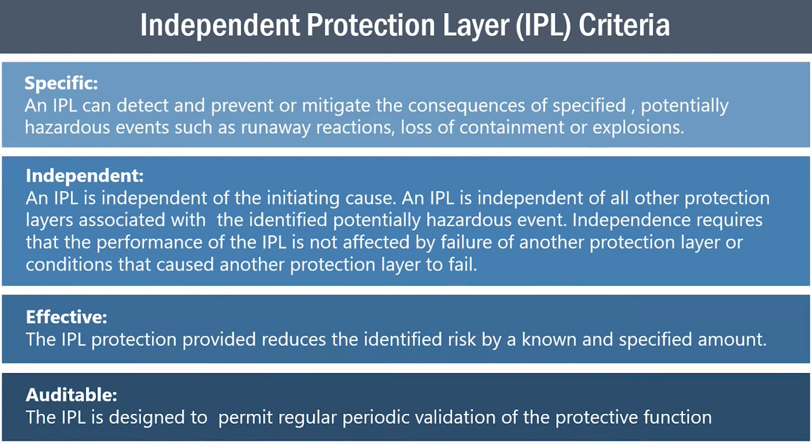The word that most people get hung up on with IPLs is independent. The IPL has to be independent of the initiating cause, and also the IPL is independent of the other protection layers associated with the identified potential hazardous event. So let's go back to our little example again. Our operator is watching the PLC and opening the valve, watching the transfer of the acetone into the tank, and at a certain point we'll turn it off.